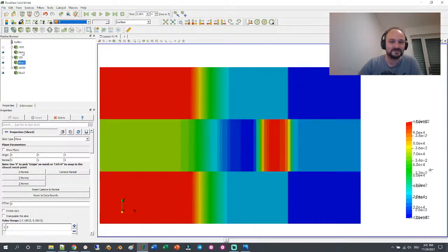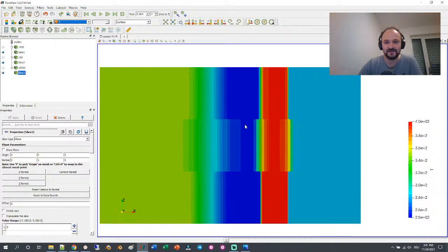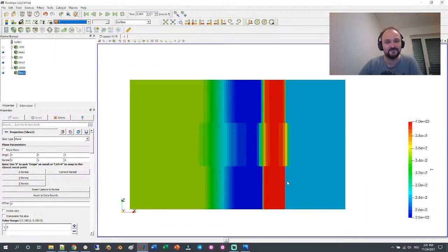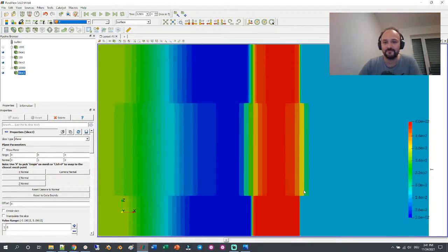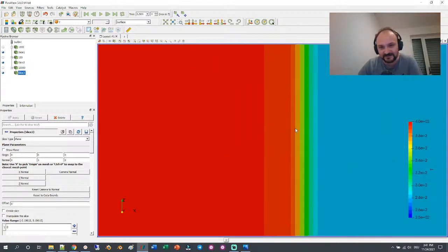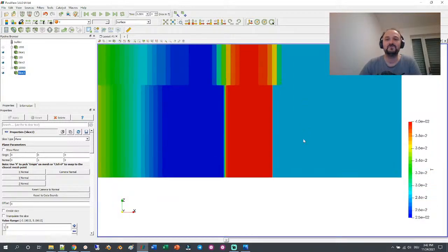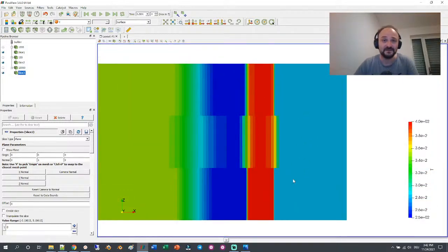So with 10,000 cells you are very exact. So here also in the temperature you can see that this is a very, very sharp jump, but if you really zoom in, then you can see that there is a numeric diffusion here, but since the mesh is so fine, you can remedy the numeric diffusion with the cell refinement.